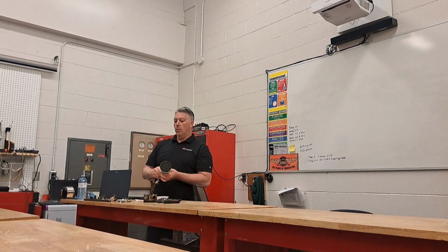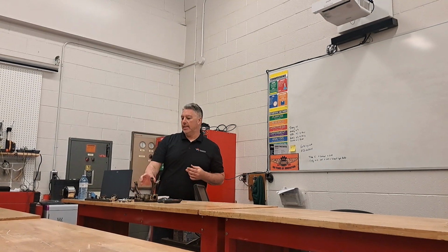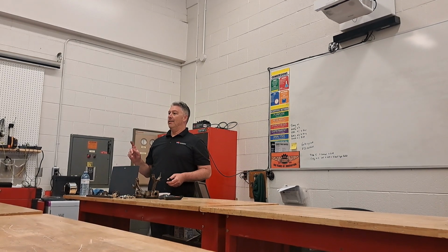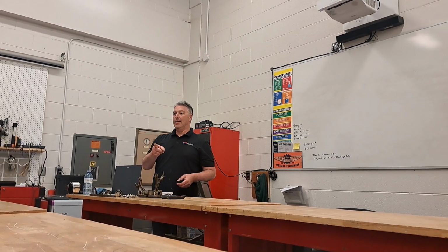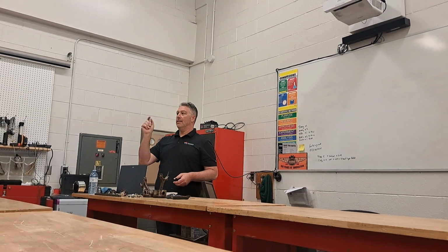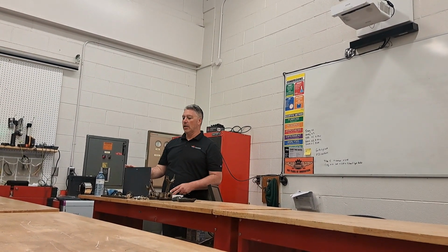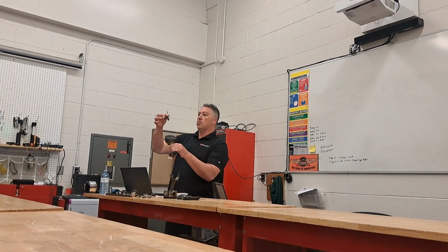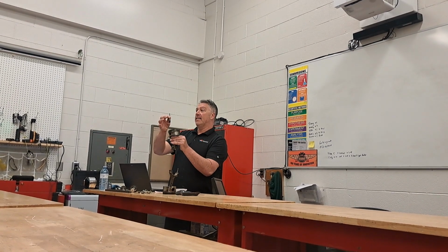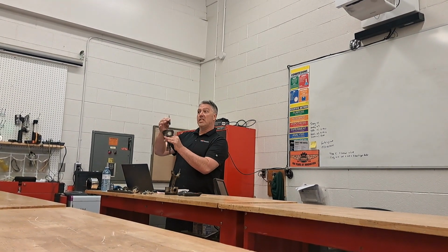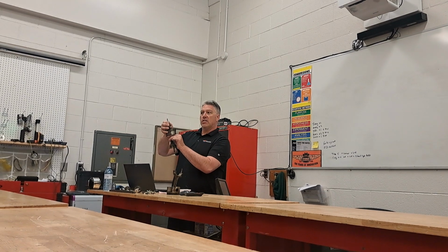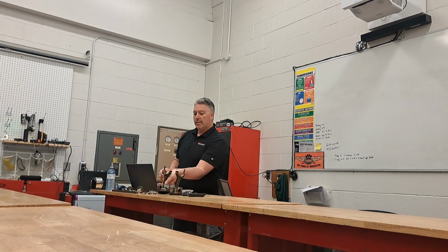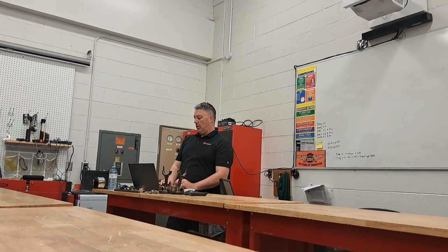Explosions, air and fuel. What are 3 things an engine needs to start? Air is one, yes. Fuel is another. Spark. Air, fuel, spark. If there's one of those missing, say the spark plug isn't working, it's dead, it's broken, whatever, then this cylinder becomes dead. This cylinder no longer runs. So this vehicle will be running on 3 cylinders. What do you think would happen if it's only on 3 cylinders? It'd be boom, boom, boom. You really feel it. It'd be misfiring. So everything's got to be working. Everything's timed perfectly. Everything's got to be running properly.